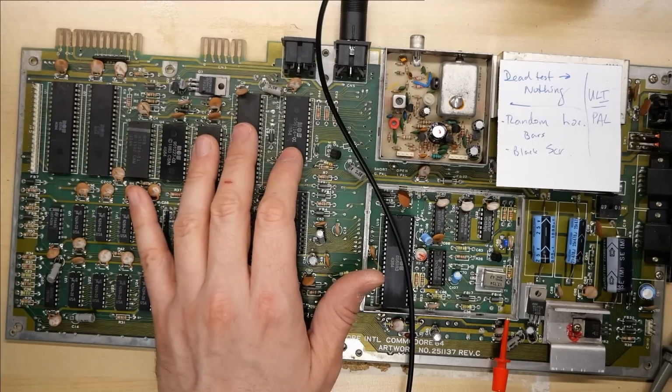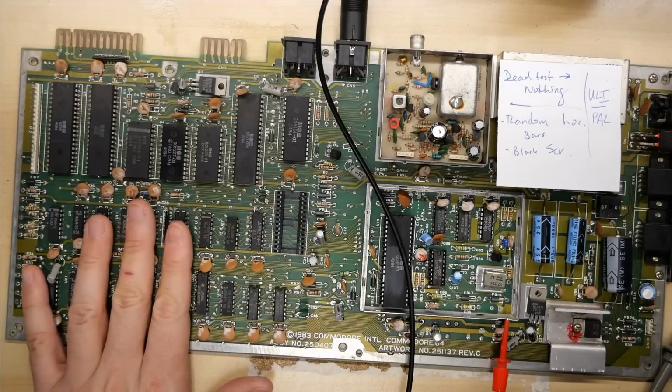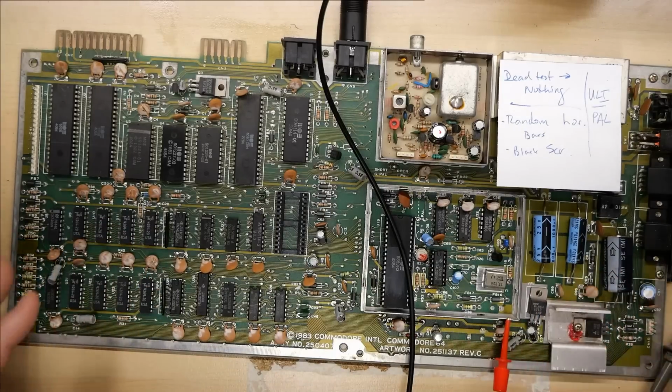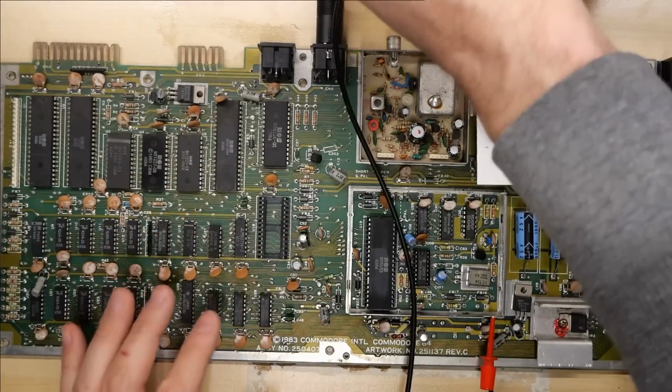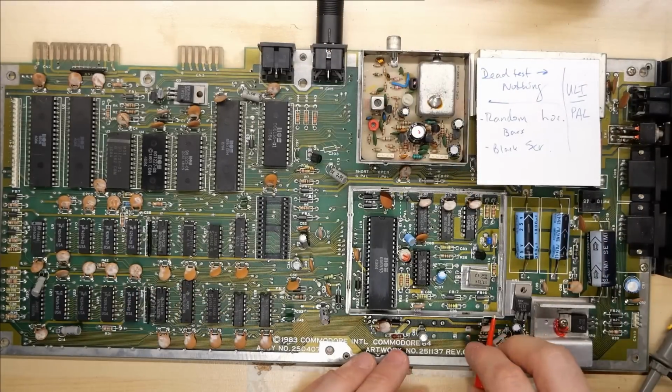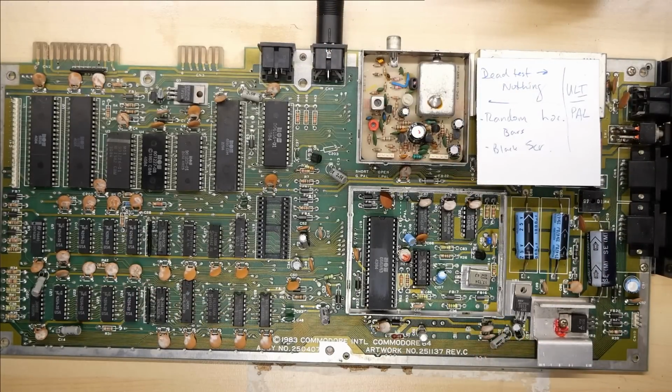It's more than likely the problem, to be honest, and this empty RAM. So this machine probably has multiple faults. So I think the first thing I'm gonna do is remove the PLA chip, desolder that, and we'll try a replacement, see if that makes a difference.